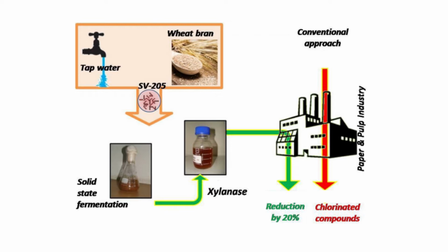So far, 2 methods have shown promise in the use of enzymes for bleaching, one using hemicellulase enzymes, and the other ligninolytic enzymes. Hemicellulase enzymes are used commercially in pulp bleaching. The main enzyme needed to enhance the delignification of kraft pulp is reported to be Endo-β-xylanase, but enrichment of xylanase with other hemicellulosic enzymes has been shown to improve the effect of enzymatic treatment. However, ligninolytic enzymes, unlike xylanases, attack lignin directly, and hence are more effective.